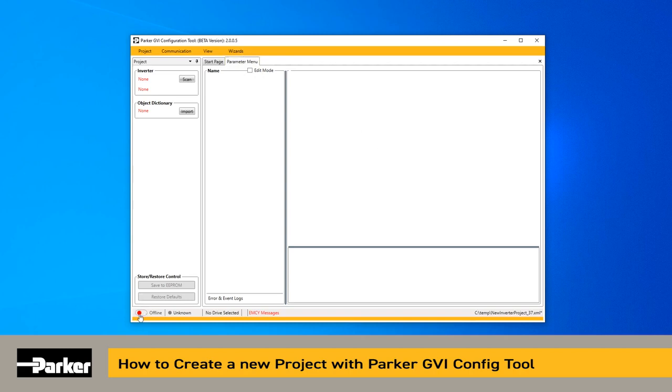The final menu here is the wizards menu, which is just a repeat of the wizards on the start page. At the bottom we have a button for making the inverter go online, which is the same as the communications go online command. We have a CANopen status indicator, and an inverter name indicator here. The emergency messages which happen on the CAN bus will show in this area here. And over on the far right we have the current project name.